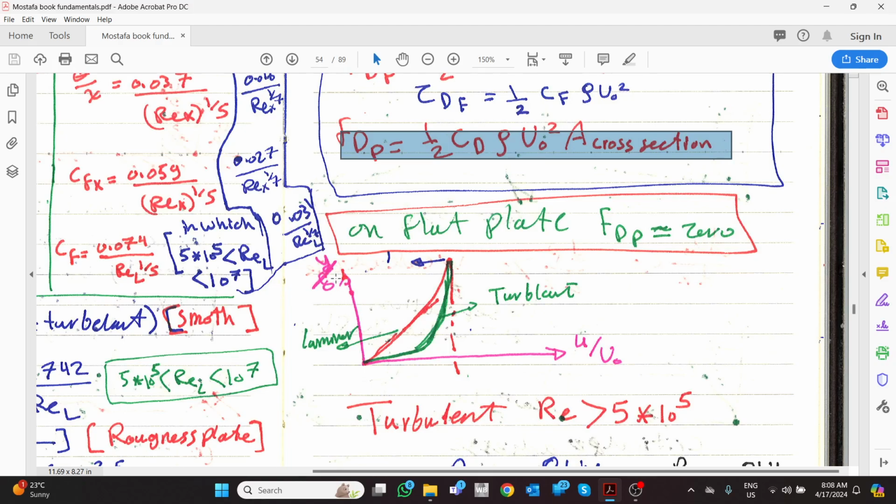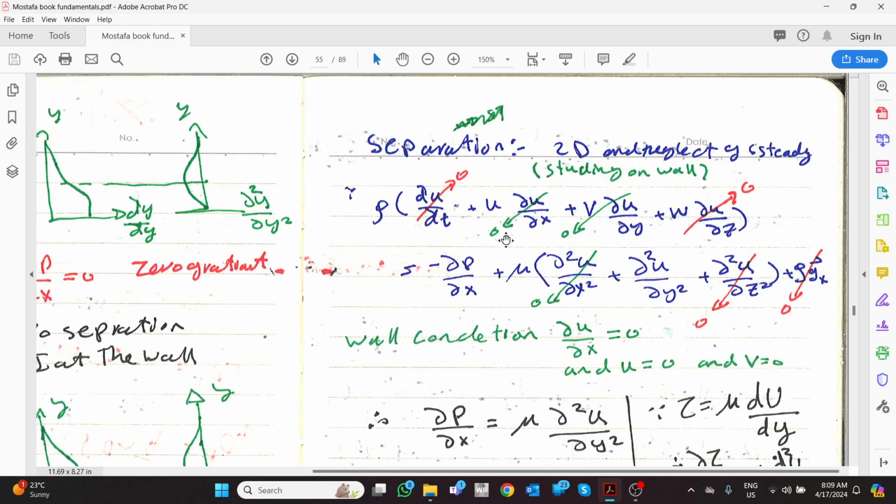This point is also just for you, that is y over delta from before. You can see the change in u over delta and the change here. Which means the laminar flow gives more shear force, by the way. Turbulent flow gives less shear force. So they will tell me, okay, it's better to have a turbulent flow if I don't want the shear force. But wait, turbulent flow has something very dangerous, which is the separation.